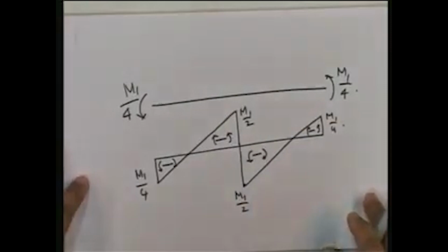Here I am just going to quickly state how we went about applying the displacement method. We found out the kinematic indeterminacy, then found out the degree of freedom. The next step is, corresponding to the degree of freedom, give a unit displacement and find out the displaced shape of the structure.